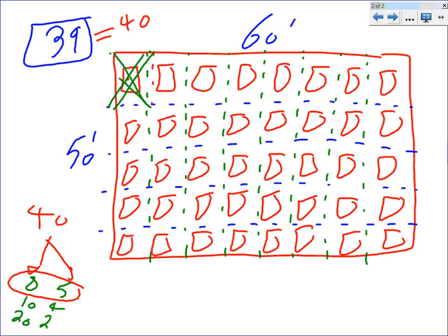You don't want one to be like 100 foot candle, the brightest spot, and the darkest spot to be 20. That's way too high. The max to minimum is too high. That's why distributing this way will give you the best average and the best distribution, meaning the maximum foot candle to the minimum foot candle will be very close to each other, meaning the ratio is going to be small. And this one was 80 foot candle average. That's the average, okay?